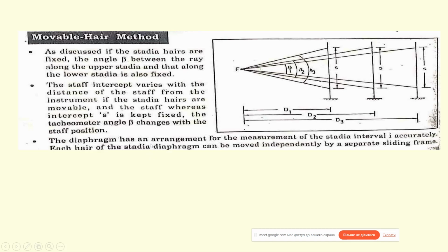The diaphragm has an arrangement for the measurement of the stadia interval accurately. Each hair of the stadia diaphragm can be moved independently by a separate sliding frame.